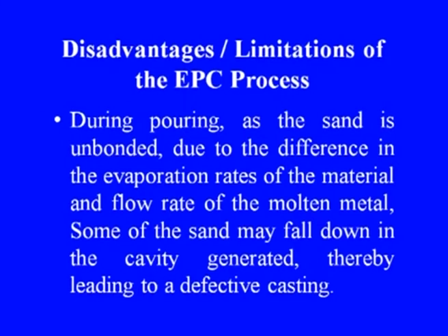During pouring, as the sand is unbonded, due to the difference in the evaporation rates of the material and flow rate of the molten metal, some of the sand may fall down in the cavities generated, thereby leading to a defective casting.